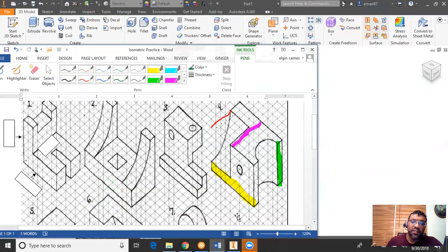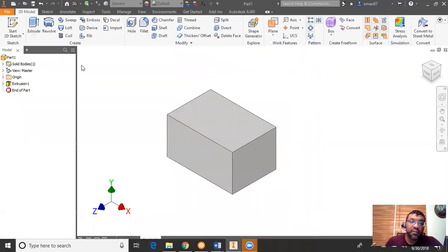All right, so the next detail I'm going to put in, I like to put in this cut right here. The radius of this cut goes from the center of here to here. So that radius is going to be 2 boxes. So it'll be 2 times 0.5. I want to show you an option here to do this. I'm going to go to 2D sketch. When I click on this, I want that curve, a cut, to exist on this edge right here.